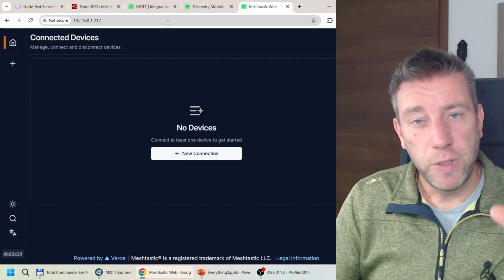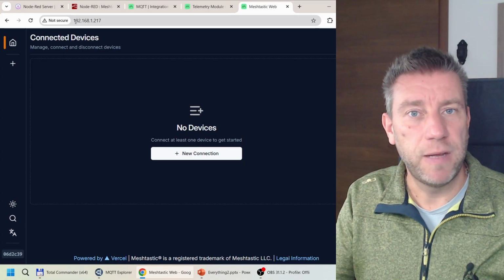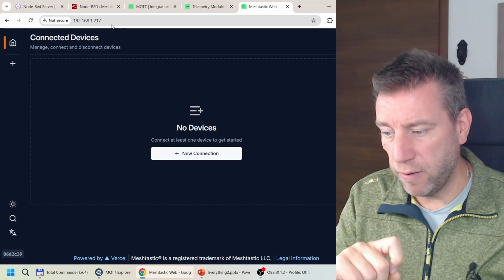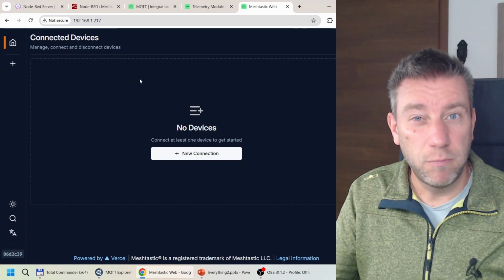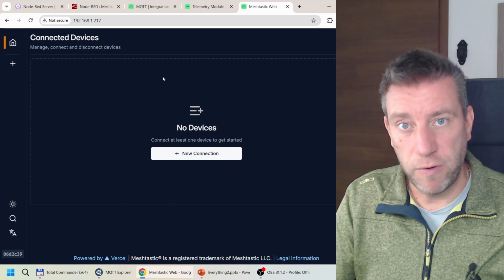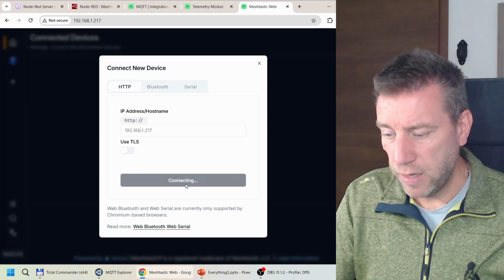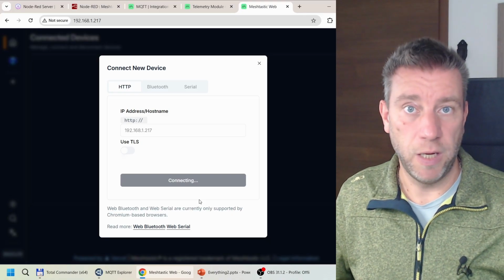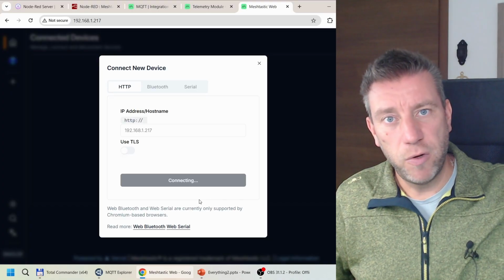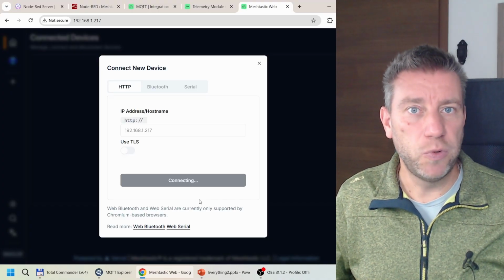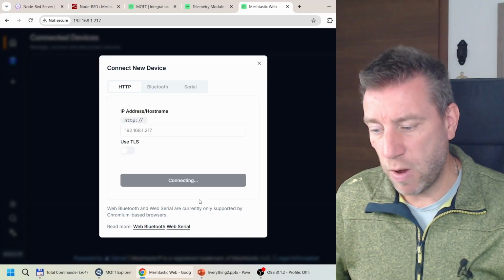And first I'm going to show you the Wi-Fi node configuration, and for this I have typed the IP address of this Wi-Fi node, and this loads this client interface, which you can use to configure any Meshtastic device. So I'm just going to set up a new connection, and I'm going to connect it locally, and that's going to load the administration. It's saying what you can access on the phone, but this node is a little bit further away from me. I cannot connect to it using Bluetooth, and the remote configuration is not enabled.